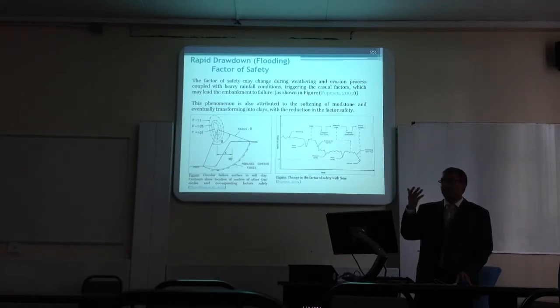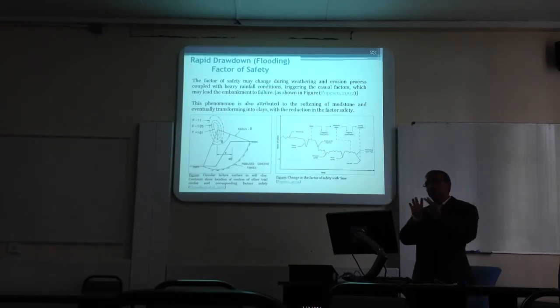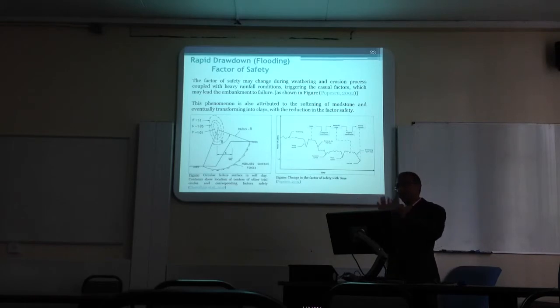So I think, again, it needs further development for the clay, different kinds of clay like Gault clay and London clay, which exhibit a deterioration with time, like 10 years, 20 years. Then you can take that into consideration and apply it accordingly to get the factor of safety, a conservative factor of safety.